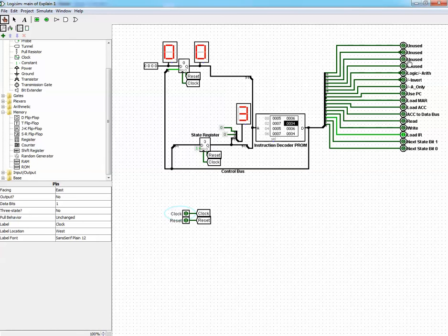So why didn't we put them down to only 12 bits instead of building a 16-bit ROM, instruction decoder ROM? The reason is because in the market, if you want to implement this in hardware, you'll always find that either it is an output of 8 or 16 or 32 and so on. So this is why you'll not be able to find an output of only 12 bits.